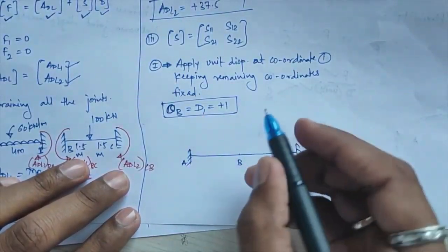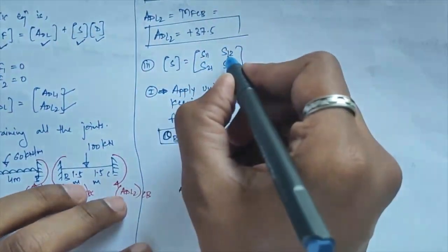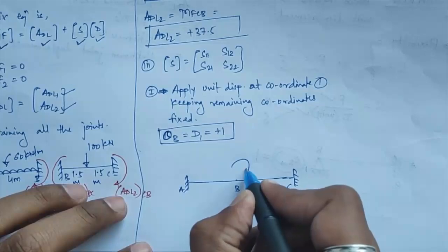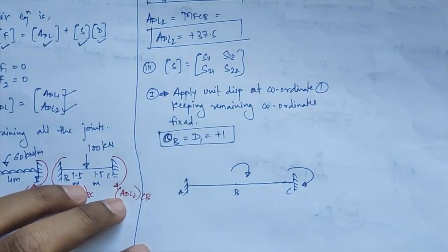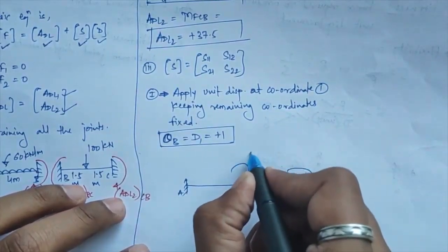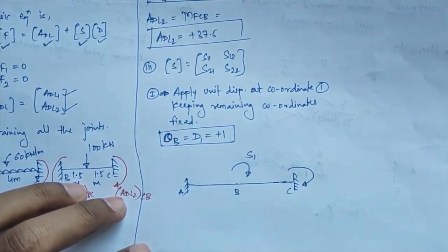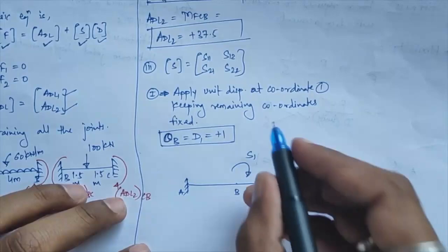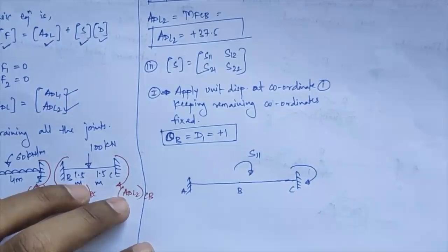Here first you have to apply the stiffness forces over here. Okay, so here I'll mark the two forces, those I am getting from stiffness over there. Okay, now which are these forces? Stiffness you are calculating at your first coordinate, right? When unit displacement is applied at your first coordinate, like F11, F12, those we are calculating.